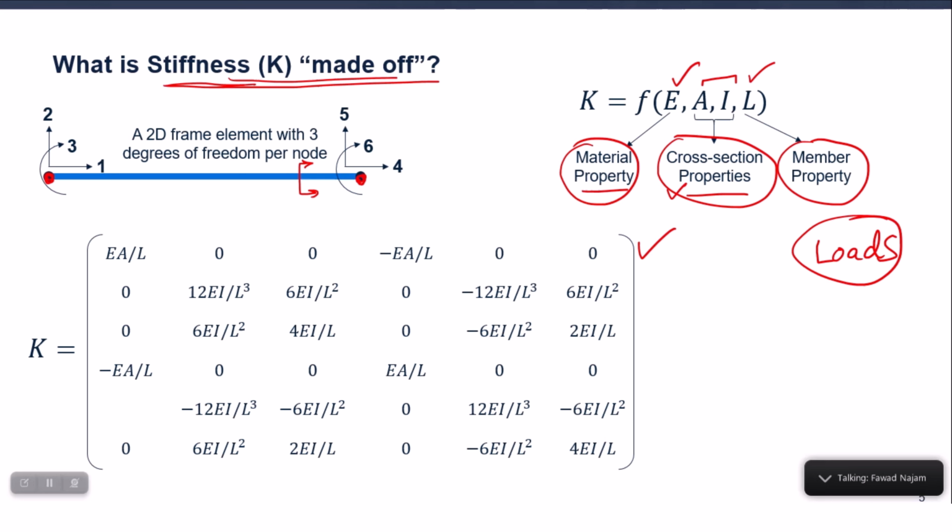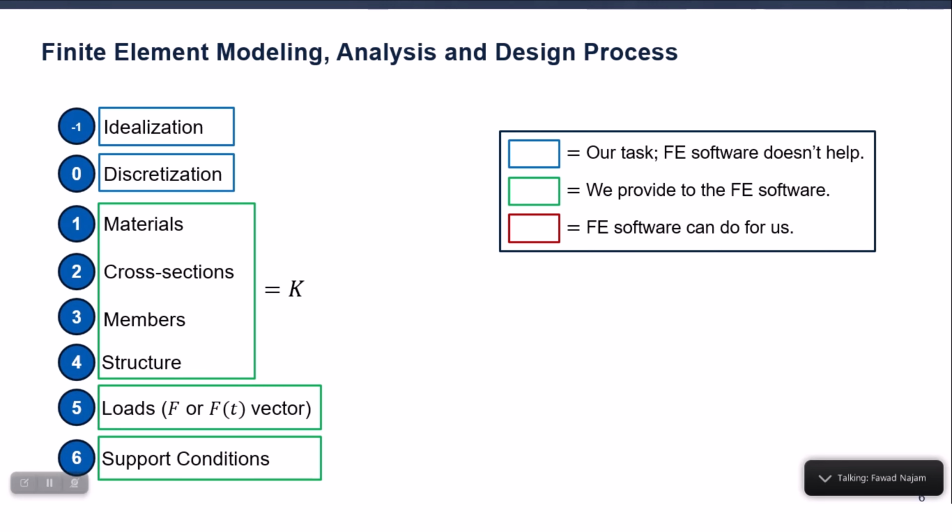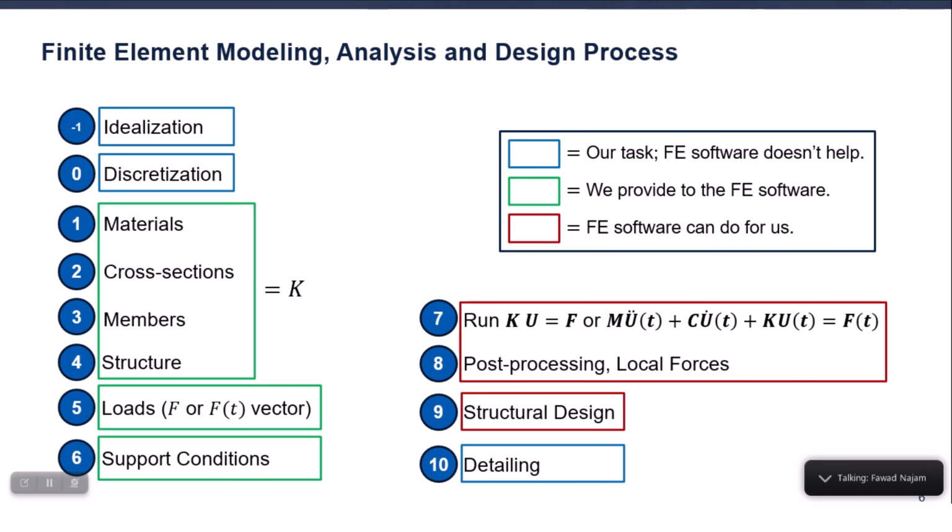The process is also mainly in the same order. You start with defining all the materials, then you go to defining cross sectional shapes. The next step is you start drawing the structure, which means you are giving the lengths of different elements, and finally when the model is complete you apply the loads and give the information to construct the F vector, the applied loading vector, right. So, if I just summarize the whole process, a kind of workflow in any finite element based program,